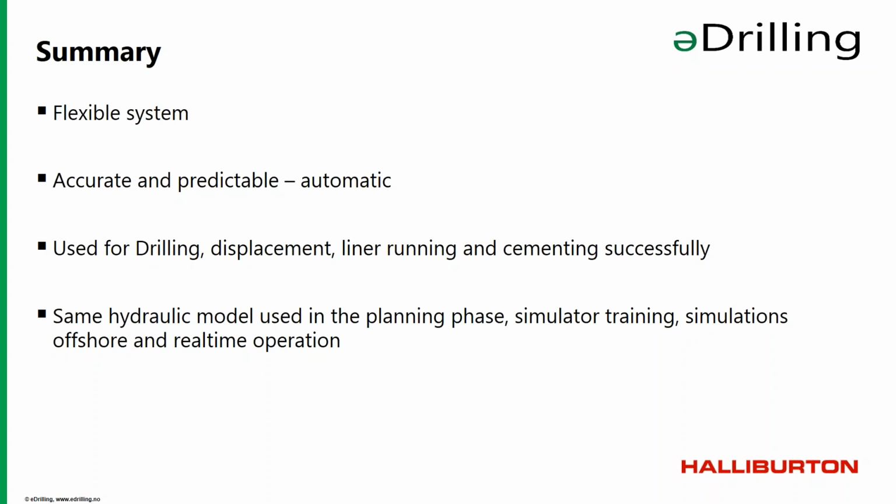Okay, another question. What would be the benefit of using MPD as a wellbore breathing mitigation technique in overbalance mode? I think the good thing here is that when you're running an MPD system, you are running a constant pressure at your problem area. So you would be avoiding wellbore breathing mainly.